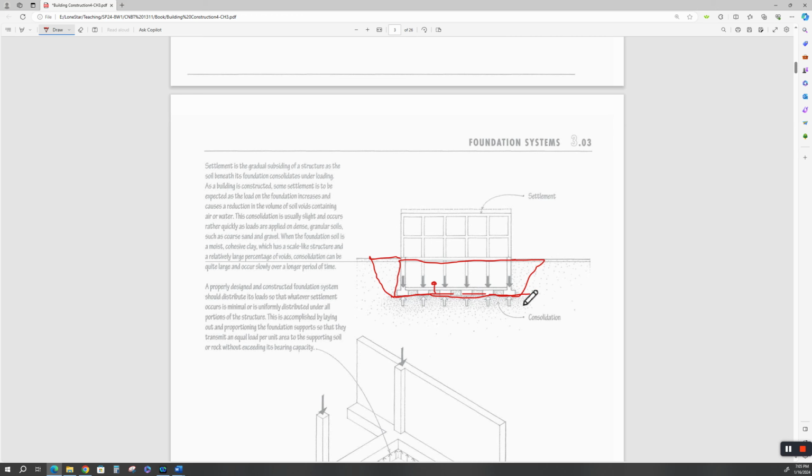Once the concrete's laid in, then we start benching the backfill. And we use heavy compacting equipment, rollers, compactors to compact this soil, and sometimes the compaction force is much greater than what would be the passive force of the soil once it gets put back in place. So your engineer has to design the wall for the construction forces against this as the stuff's being compacted.